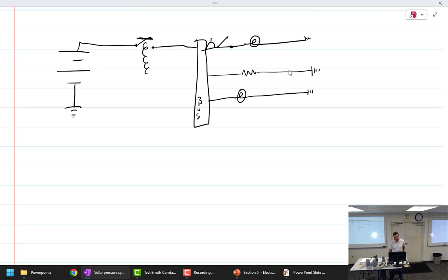This is a ground wire, and literally components on an aircraft, like that light bulb, have one wire going to the light bulb, and then one wire comes out of the light bulb that is that long and just goes to the aluminum frame on the aircraft. So electricity is literally, in a metal aircraft, going from the battery through a cable that far to the aluminum frame of the aircraft. Electricity flows through the entire piece of aluminum, comes back through the little wire, goes to the light bulb, lights up the light bulb, and then follows the positive wire back through the switch, back through the circuit breaker, back to the master solenoid, back to the battery. Literally, that's what it is doing.